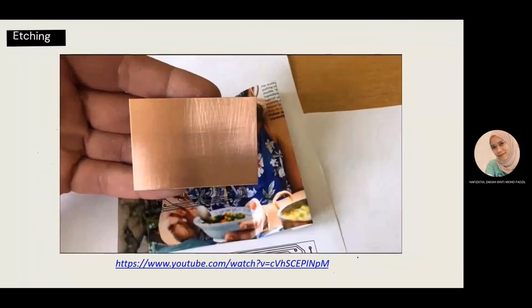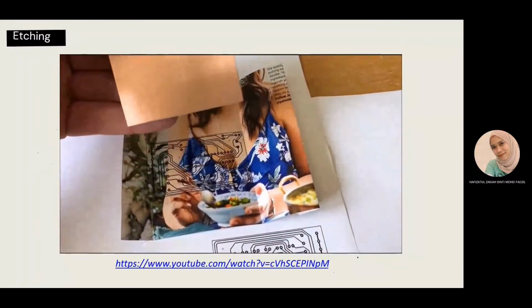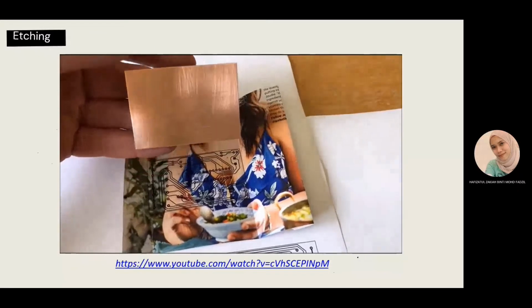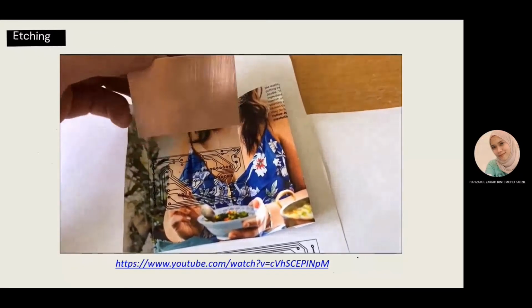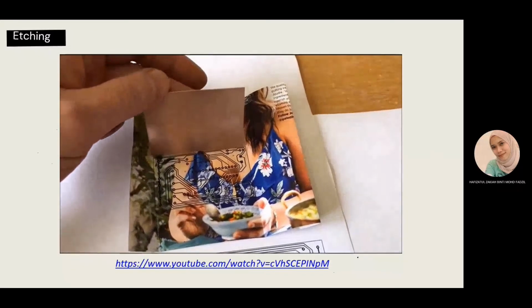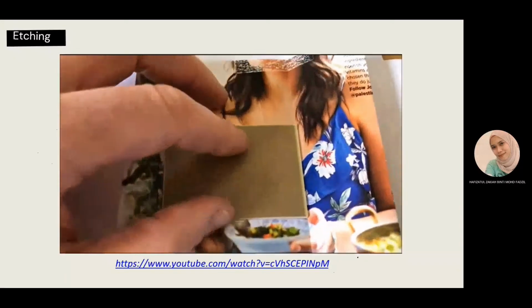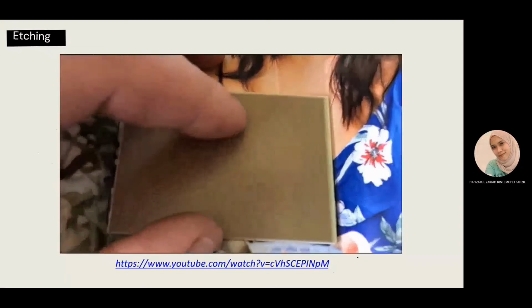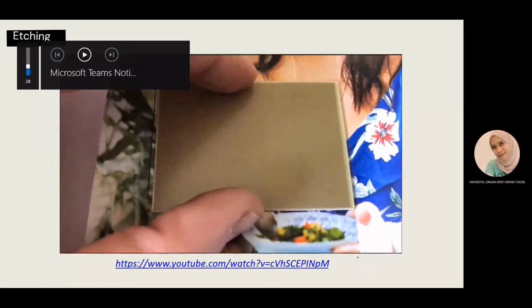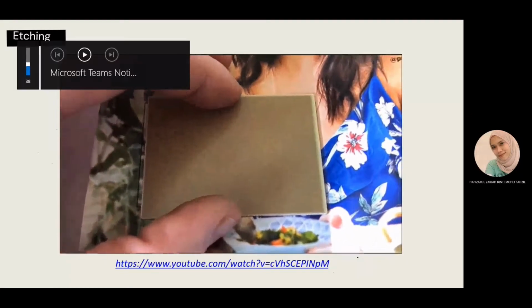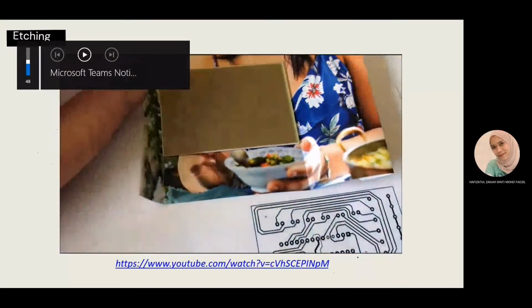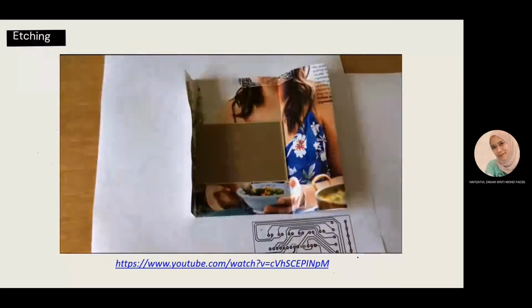Onto the copper board, I use magazine paper, just local supermarket magazine. Pages are glossy. The only thing it'll transfer onto the copper board from when you print on this is the actual toner, so it's ideal. So we'll go ahead and place one of these over this image so we know it's going to print in the right place.